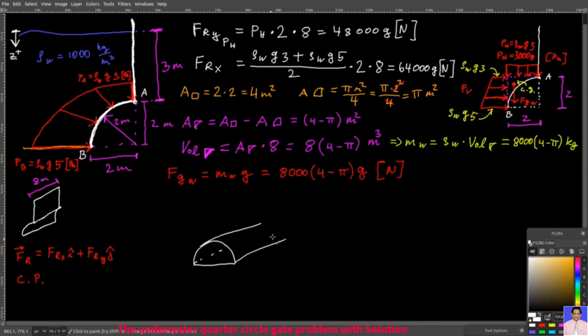When we dealt with the underwater tunnel, we calculated the forces per unit length, in newtons per meter. We had WR here, and it was along the tunnel. That's because we did not know, nor did we care about, the actual length of the tunnel. We simply knew the tunnel's depth underneath the water, and thus this WR was constant along the tunnel's length. So we kept our calculations in newtons per meter, and also in kilograms per meter.